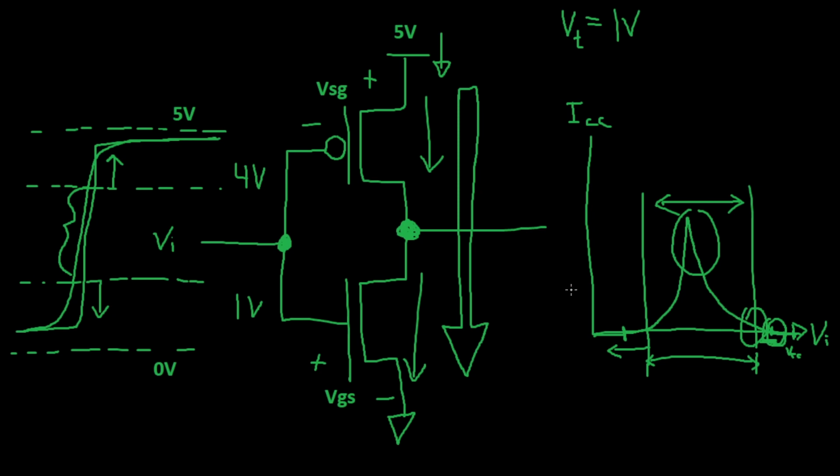There's one other reason why you don't want to transition states slowly on the input of a CMOS device, and that's because of possible oscillations. There is a not insignificant amount of inductance on the wires that connect the supply and ground internal to the device. Whenever this sudden current flows through those, it can cause a voltage to appear, and that causes your input threshold to shift.